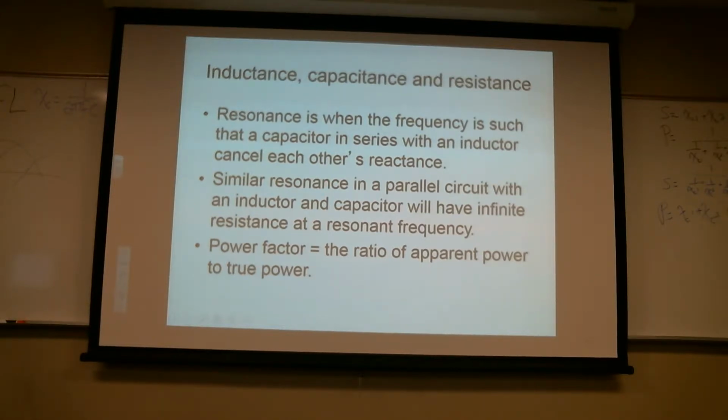If I lowered the cycle, because inductive reactance goes down when I lower the frequency, and capacitive reactance goes up when I lower the frequency. If I lower the frequency from 60 down to 55 or 53 or some number, there'd be a point where the ohms of inductive reactance goes down and capacitive reactance goes up to where now they're both exactly the same. X sub C equals X sub L, it goes to 0.